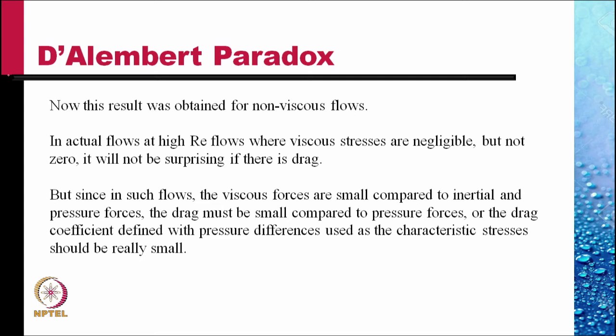And it is not surprising that it is not zero, because we are neglecting viscosity. So, in the presence of viscosity, there would be viscous stresses, and hence the presence of drag would not be surprising. But since in such flows the viscous forces are small compared to inertial and pressure forces, the drag must be small compared to pressure forces, or the drag coefficient defined with pressure difference as the characteristic stress should really be small.